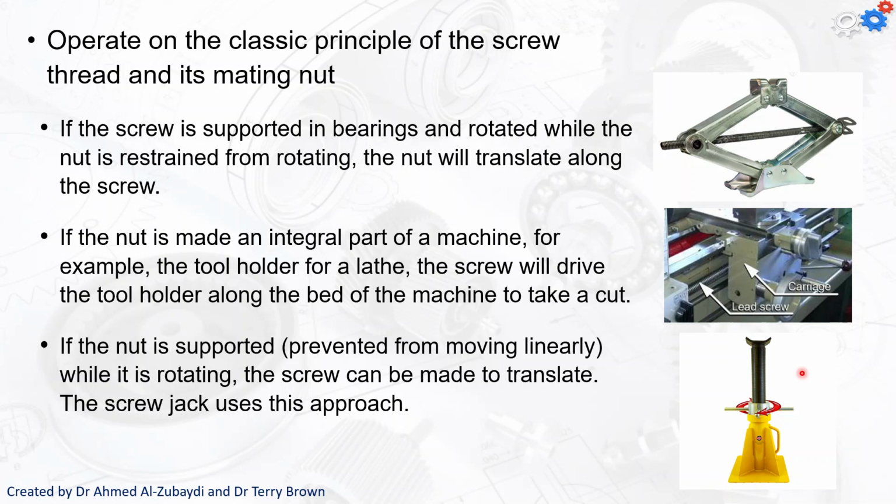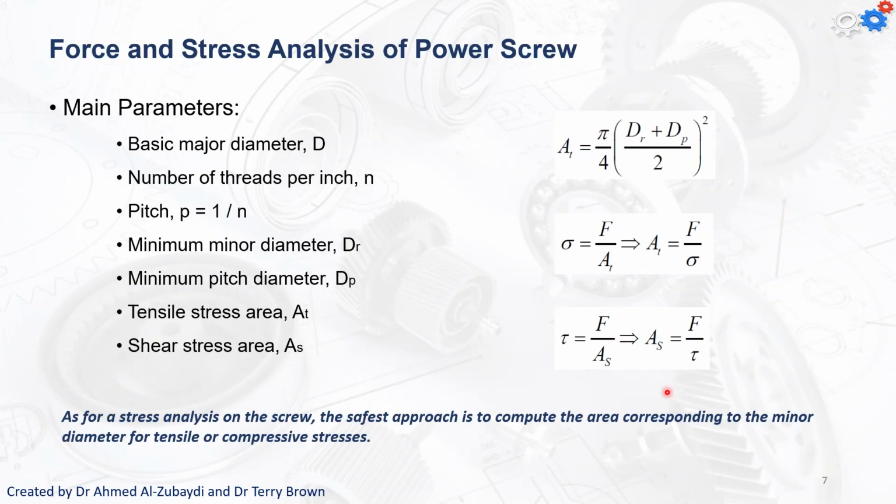And of course, one of our design requirements would be that once we take this torque off the nut here, the load doesn't just fall down. So you might be able to see, it's a little bit small, but the angle of the thread here is quite low, just to make sure that there's no possible way that the load can self-lower. But we'll look at the equations for that as we go on.